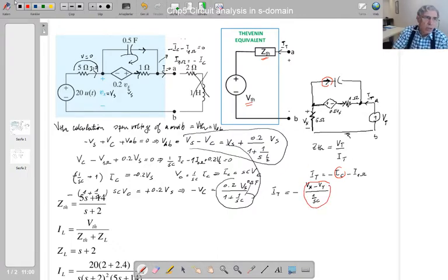So it says minus now, current of the resistor. So looking for this resistor current now. Resistor current, so what is the node voltage first? Consider this node voltage. I made a mistake, isn't it? So the sign here, positive sign on the right hand side, negative sign on the left hand side, which is the opposite. So I correct my mistake now. So plus here, minus here.